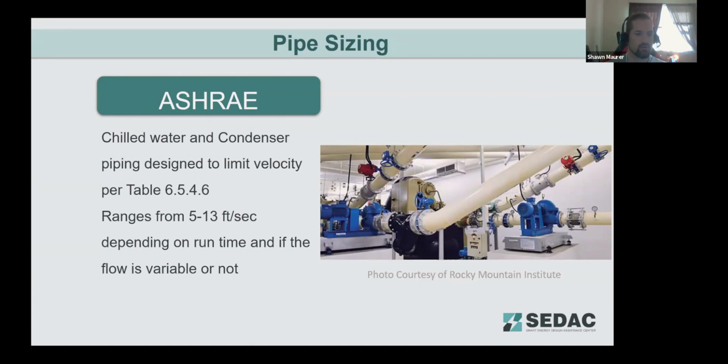And so again, ASHRAE here is just looking at that in terms of the flow rate through that piping. Looking at designs that are going to maintain that flow rate may lead you to these reduced angle fittings, and you're trading off a little bit of the floor footprint for a building for this higher efficiency. But with design of equipment, you can compensate for the pipework taking up more area by fitting smaller pieces of equipment under these lower heading areas of the pipes.